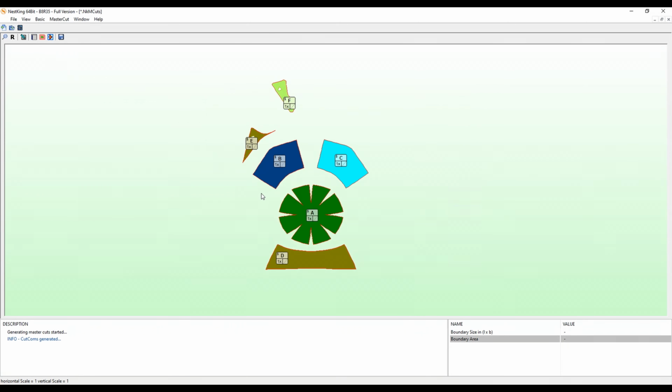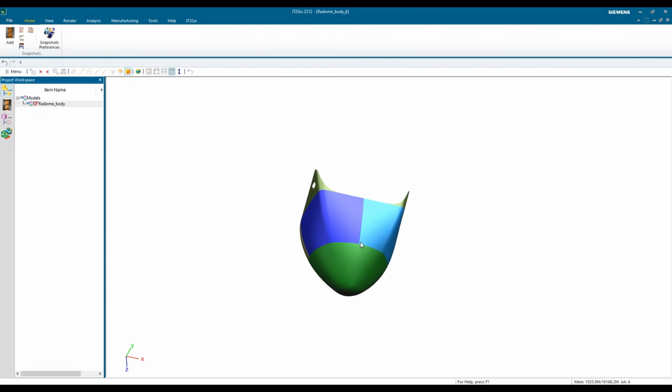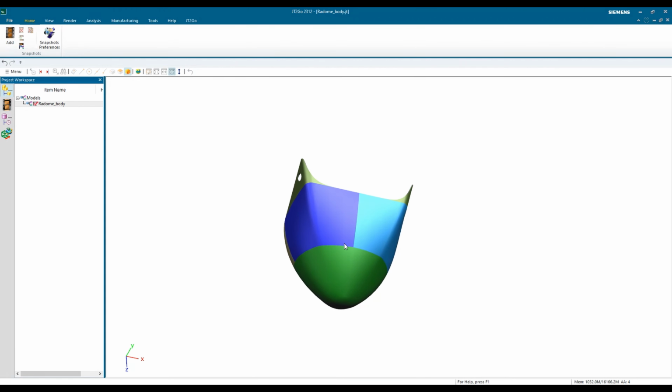And now with this, we have to go again into the sketcher and start assigning edges that we know are in contact or interfacing, and managing the overlaps. Because what you do not want is when you connect all your plies, you don't want to connect them just face to face. You want some overlap. You want to manage this overlap throughout your stack. And mainly you don't want these overlaps to occur at the very same spot.